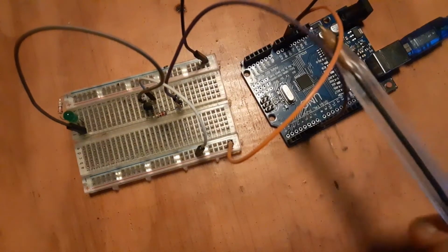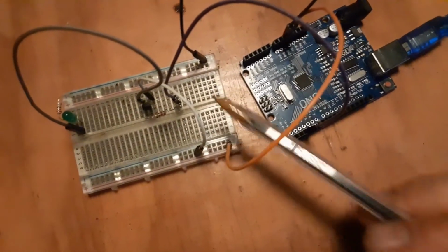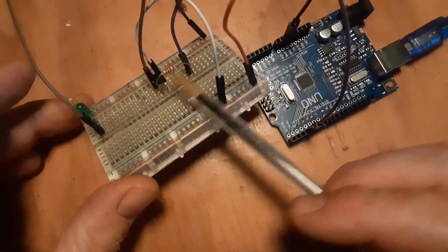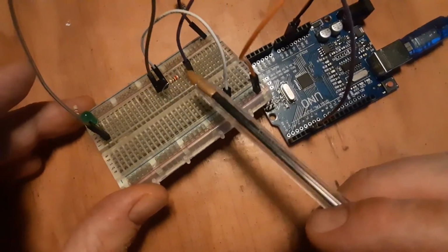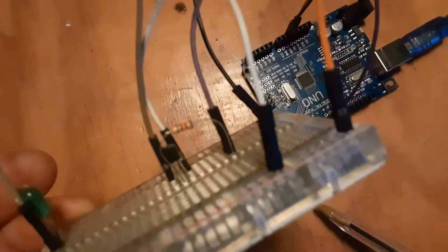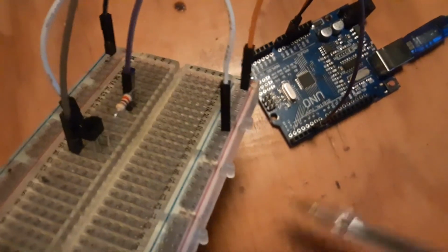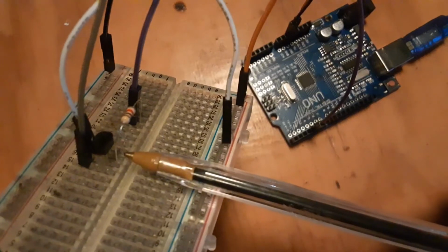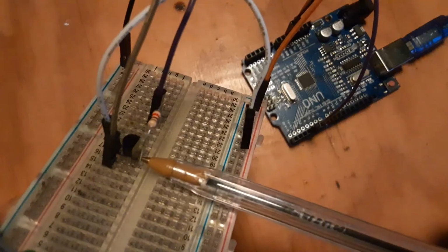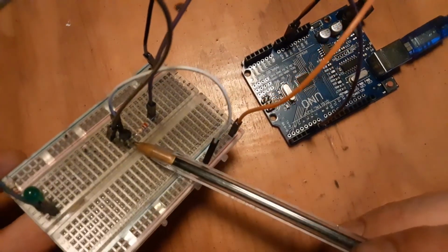if we follow that wire through, there's a little purple wire here. You see it comes over and then runs through a resistor. That's just to get the appropriate amount of current to the middle pin on the transistor. It's probably kind of hard to see there, but that resistor is feeding the Arduino pin into the base of the transistor. So that's what's going to turn it on and off. So basically the microcontroller is flipping the switch.